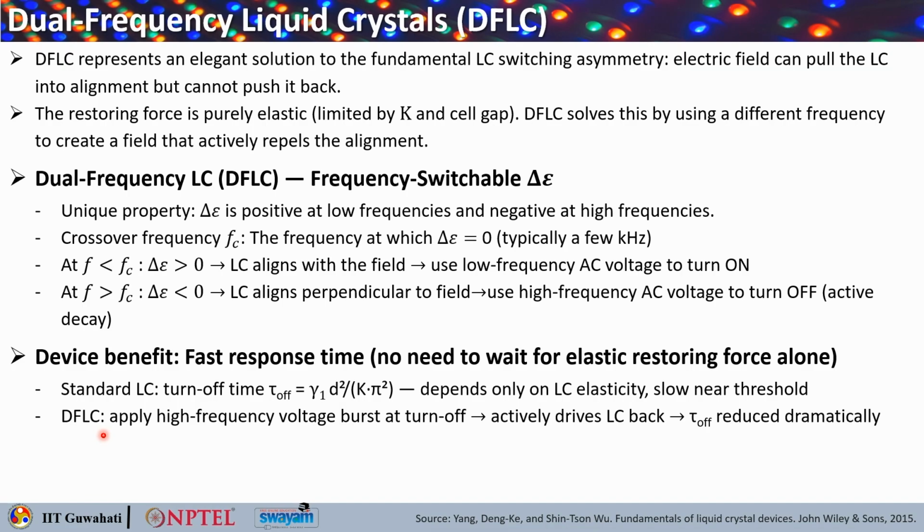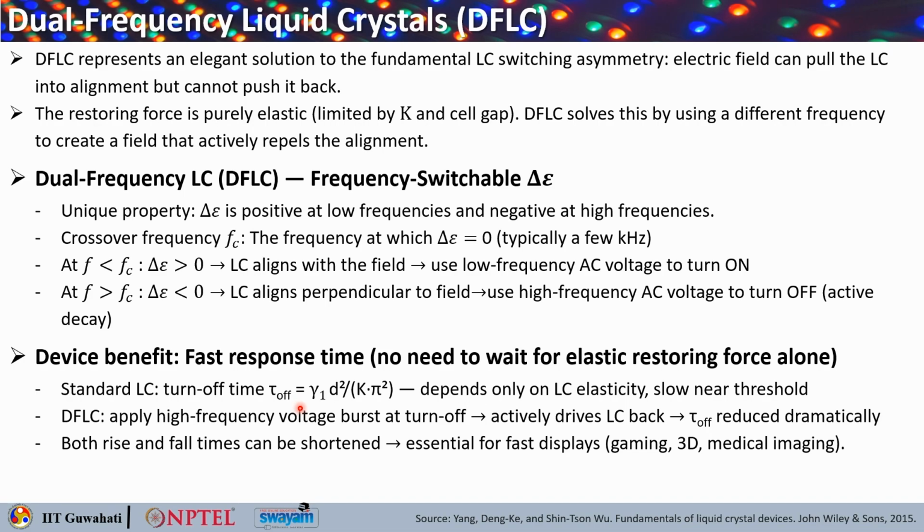So, when you have DFLC, you are applying a high frequency voltage burst for turn off also. So, you are actively driving the liquid crystals back. So, your tau off reduces dramatically. In this case, both the rise and the fall time can be shortened. So, this is essential for fast displays such as gaming, 3D and medical imaging.